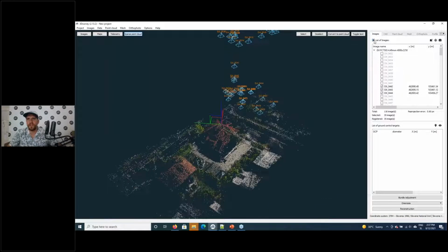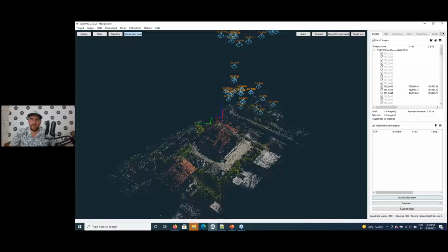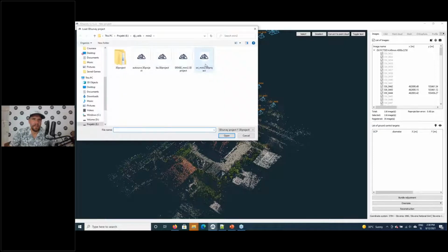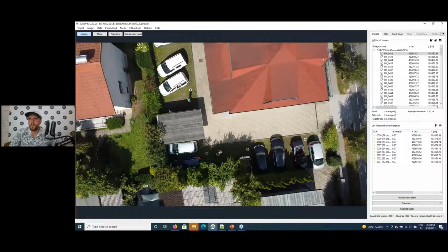So now our initial camera parameters are the same as our optimized camera parameters. That's okay. Then what we would do next, we would select all the images here, press bundle adjustment again, and then do the whole project from here onward. So that means do bundle adjustment and then also the orientation. And after we get the oriented project, at this point, we would again calculate the point cloud, make sure that point cloud is accurate.